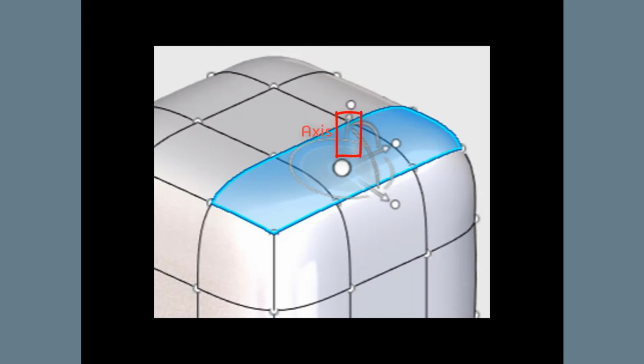Axes, marked as arrowheads, that can be used to push, pull, or drag in axial directions. Planes, marked as shaded areas inside the arcs, that can be used to push and pull in planar directions. Arcs, that are used to rotate around the axes. Scales, marked as balls at the end of the axis, that are used to scale larger or smaller in one or two directions. And a larger center ball that is used to control the orientation and position of the robot.